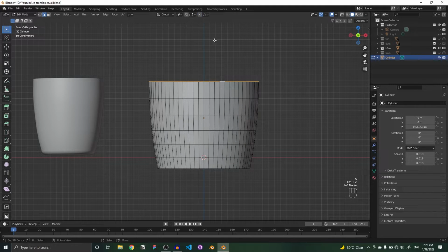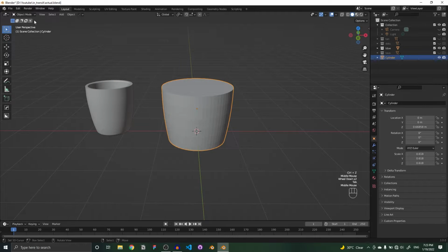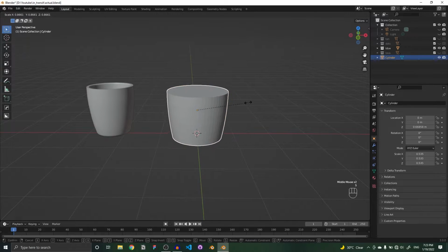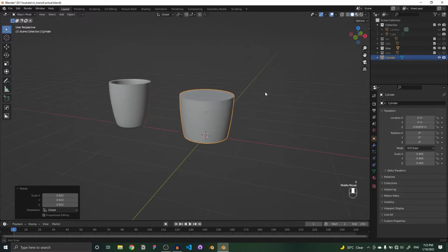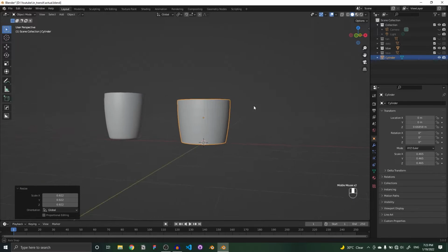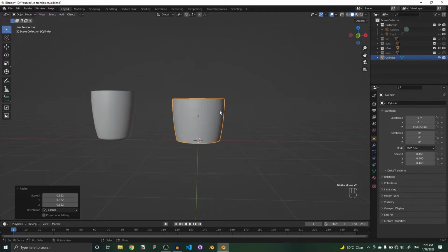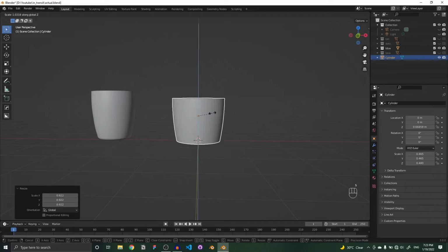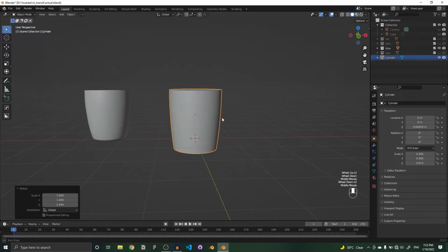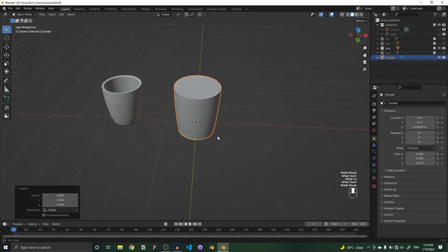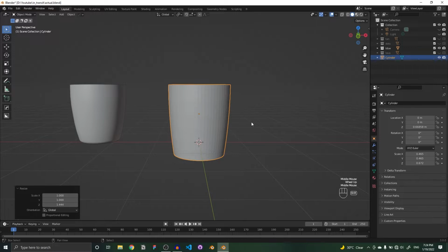Sorry, I'm going to remove the proportional editing now for the time being. I want to select the entire thing. So I shifted to object mode and I'm just going to decrease the size. All right. Now I need to increase it lengthwise. So remember we're in the object mode. Click on S, click on Z so that I can increase it lengthwise. All right, it's looking fine. A little curve would be appreciated, but let's just see.